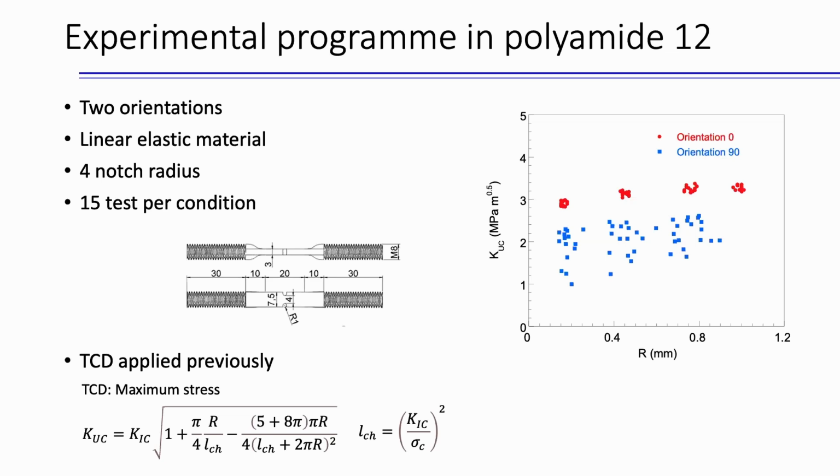Now, the idea is to fit with the failure criterion that we mentioned in the first slide. We are using the theory of critical distances, maximum stress. We are going to fit the criterion, and we are going to determine the toughness in our expression. The interesting point is not this procedure. The interesting point is to analyze the uncertainty that we are introducing with this. We have the uncertainty in the notches, but what is the uncertainty in the toughness?